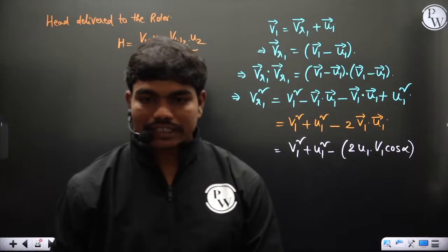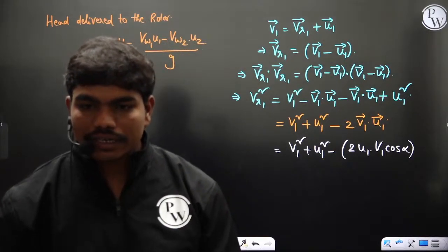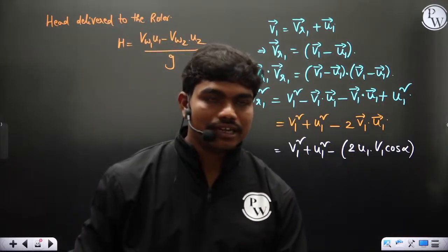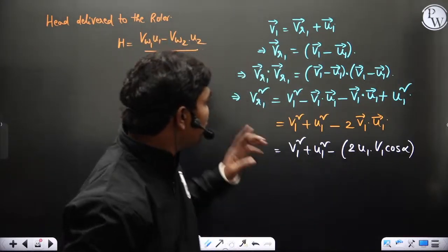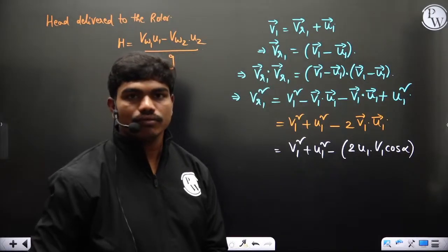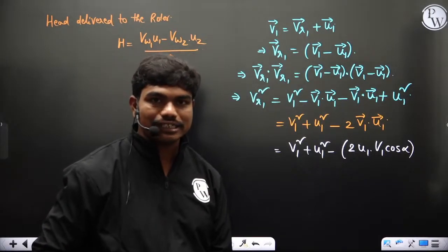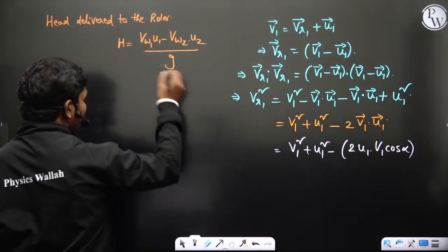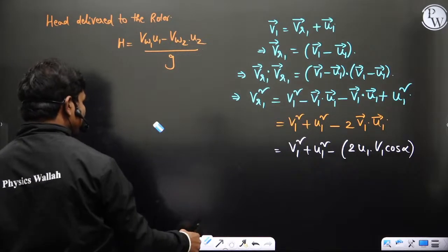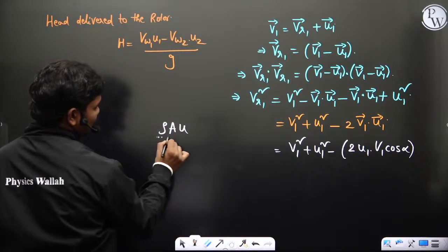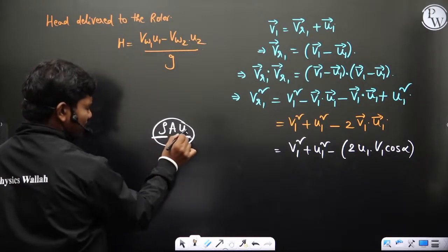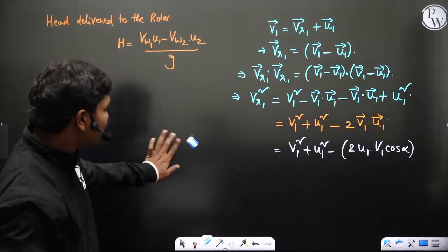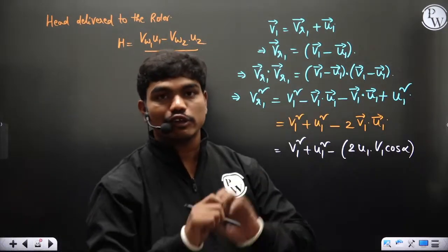For compressible flow devices, is the intuition the same for velocity triangles, like gas turbines and compressors? Normally it's not. There are slight changes depending on compressibility effects, because when I'm writing this, one important assumption that we make is no density variations. Otherwise, in the steady flow equation, we have taken this m dot out and cancelled it, but there we would get expressions in terms of velocity and density, which creates certain variation. So that's why normally in the case of gas turbines, the analysis for the velocity triangles slightly changes.